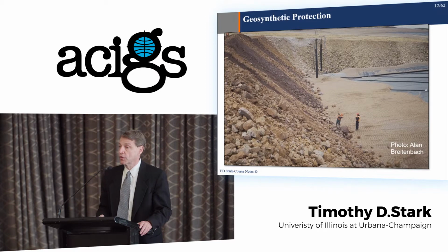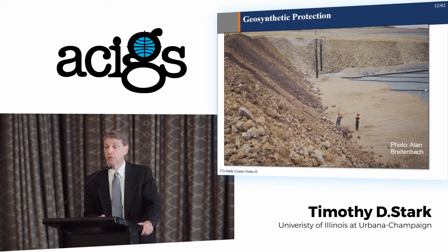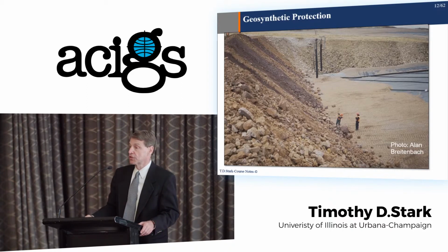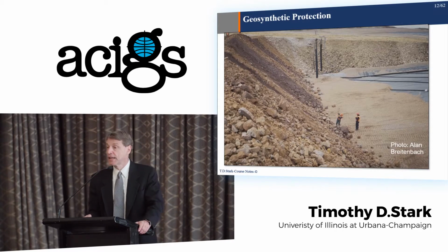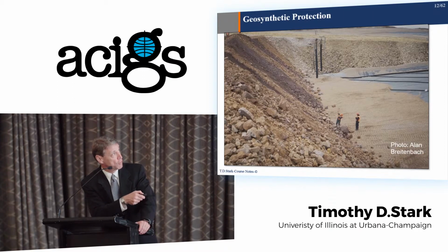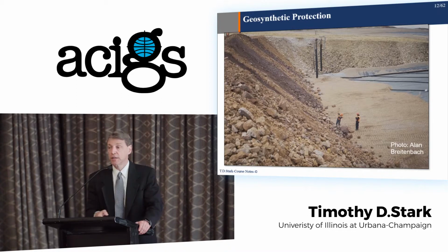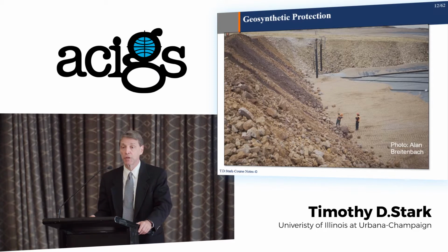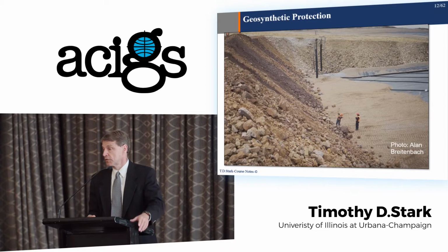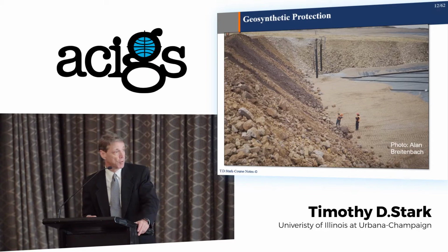Okay, one other thing, I mentioned it, puncture resistance. So we are dealing with pretty big rock here, just for scale there, and geosynthetics can be damaged by rocks that size, so we need some protection on the geomembrane. If you look to the right, there's the geomembrane. In this particular case, there's a sand layer approximately 6 inches, so that's, say, 150 millimeters thick, and so if anything rolls off the pile, it doesn't impact the integrity of the geomembrane.